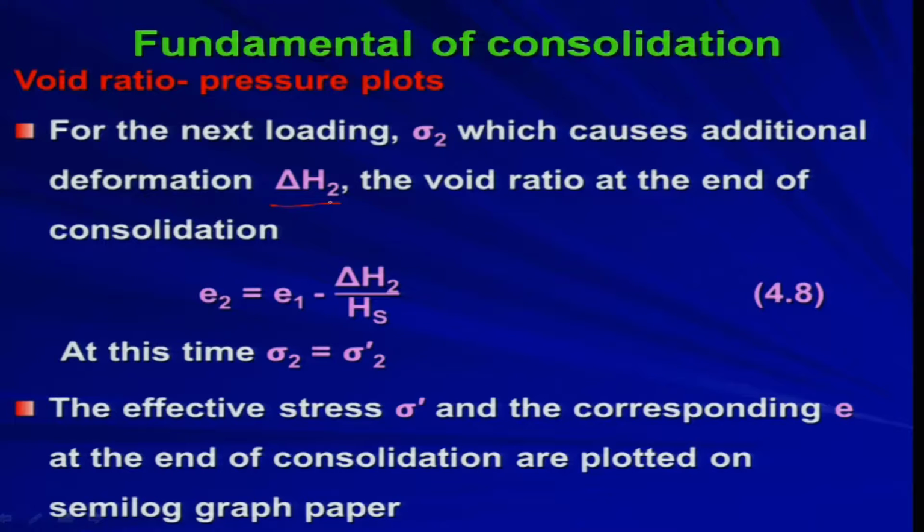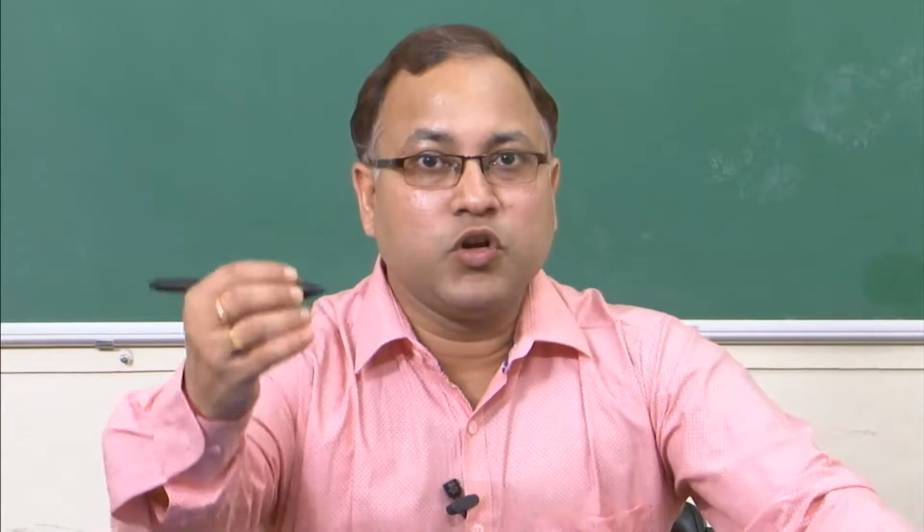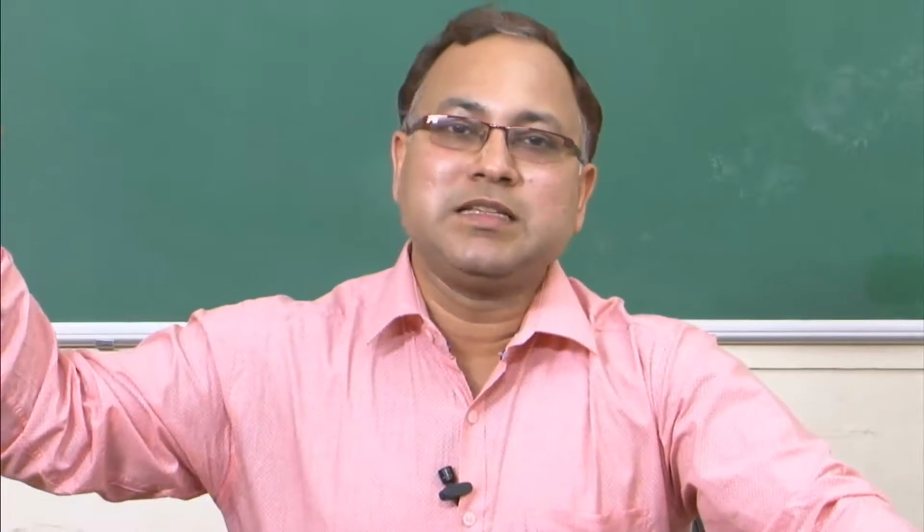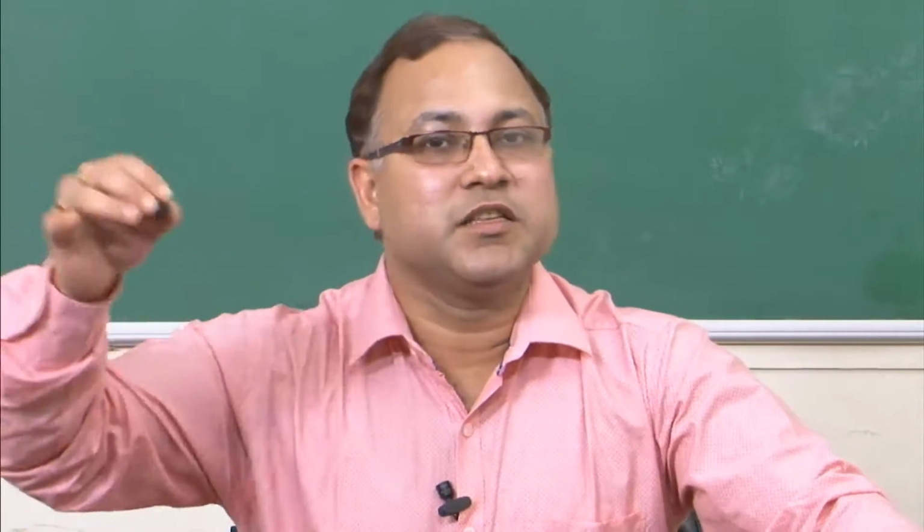So, the void ratio at the end of consolidation. Every time we are considering the end of consolidation, meaning t equal to infinity. The starting point is t equal to 0, and gradually pore water pressure will be dissipated and you will reach the point where total stress is equal to effective stress. That condition we are considering.